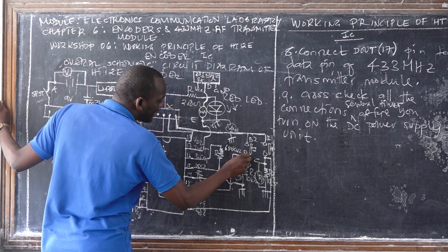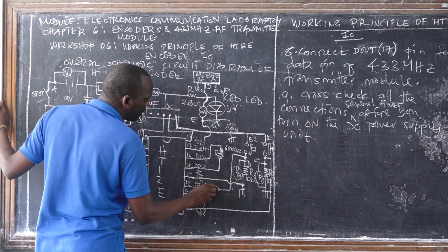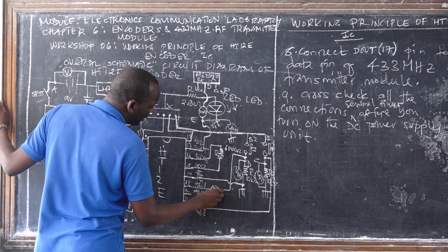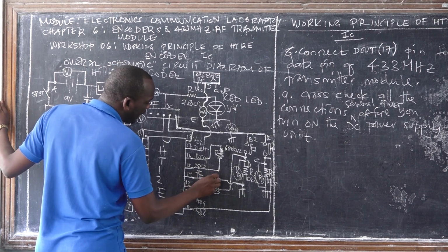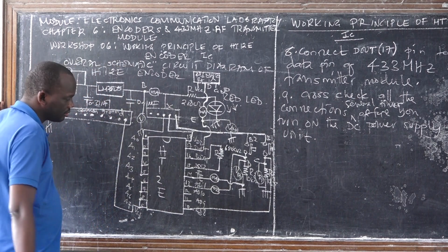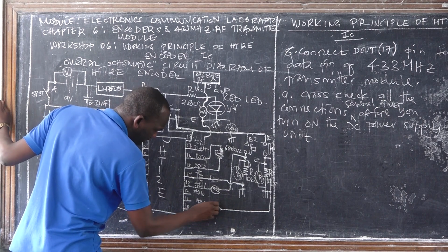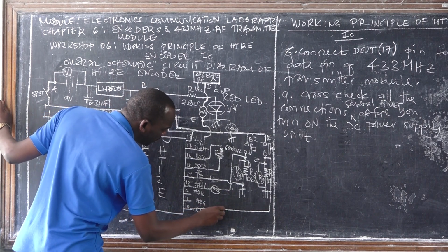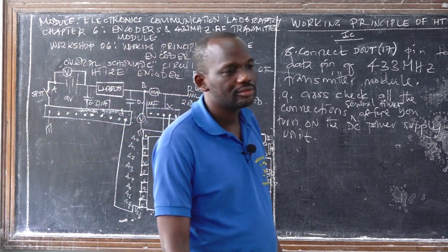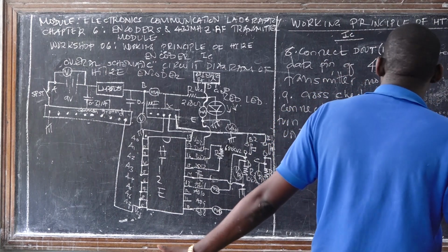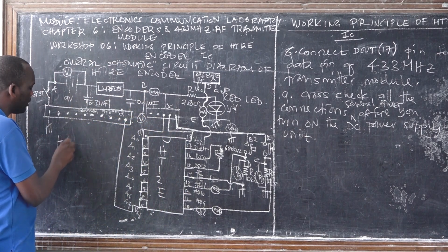Also here, stop writing. At this point, we have another measurement parameter, which is not only voltage. At this point, we also want to know the input current. So, milliampere. Oh, sorry, not at the ground. I just wanted to connect it here. So it is still one testing point, but we measure two parameters, voltage and DC current. Are we together? Yes.